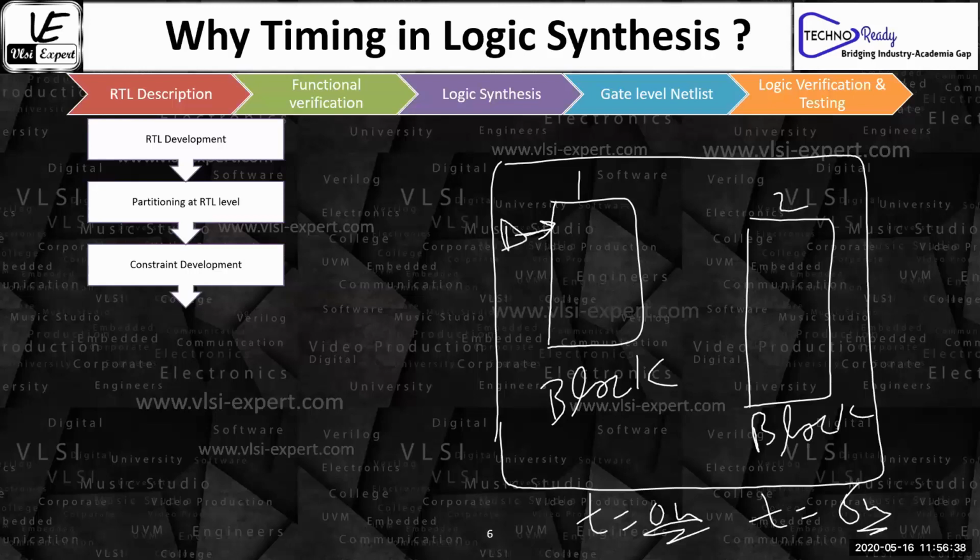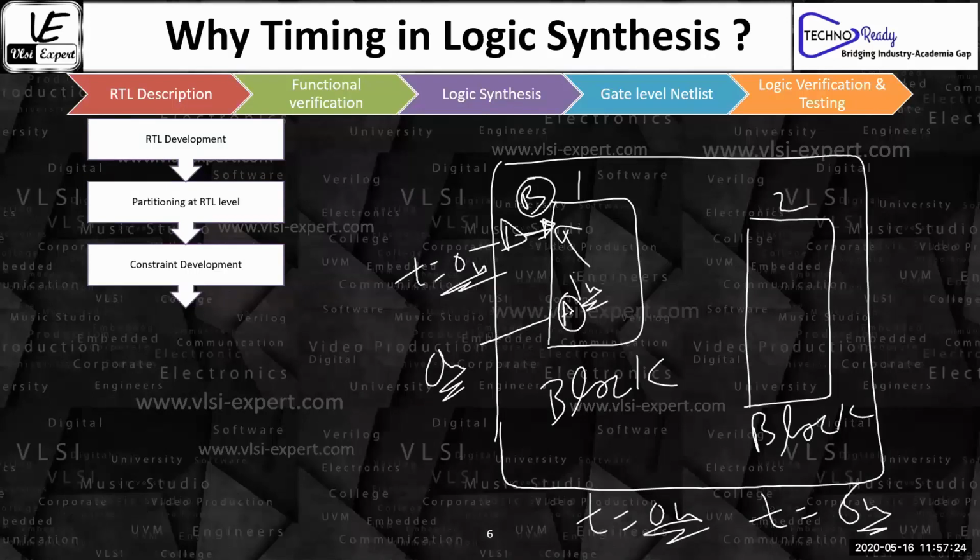Let us suppose there is a buffer here, and as an input I'm going to give 0 nanosecond. If you don't know, okay, I will get the input at this particular pin at 1 nanosecond, then you will assume you get the input at 0 nanosecond and design everything with respect to 0 nanosecond. These are the two input pins of your block, A and B. At one pin you will get data at 0 nanosecond, and at another pin you will get the data at 1 nanosecond. Unless you have this information, your system is not going to work as you are expecting. So who is going to give you this information, and in which form? These are basically the constraints.